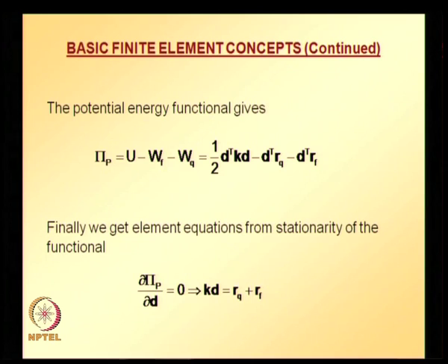Please note that these equations are applicable to any beam element regardless of how the modulus of rigidity EI and q vary along the beam length. Once these values, that is EI and q, are specified, numerical integration can be carried out to obtain the element equations. We will see what numerical integration is in a while or in later classes,